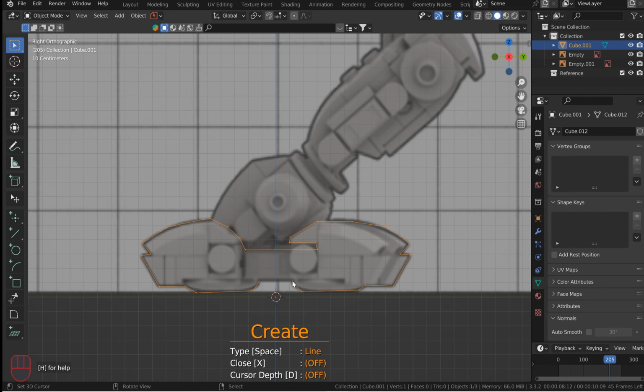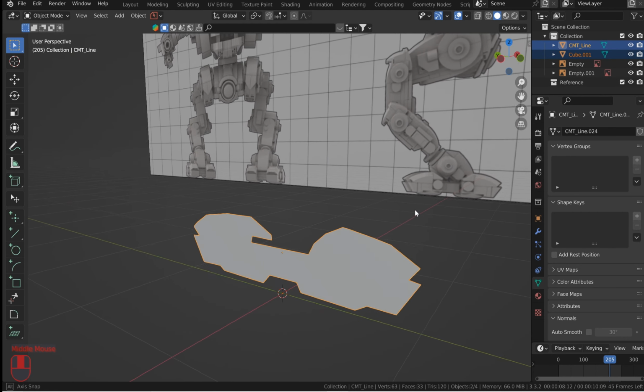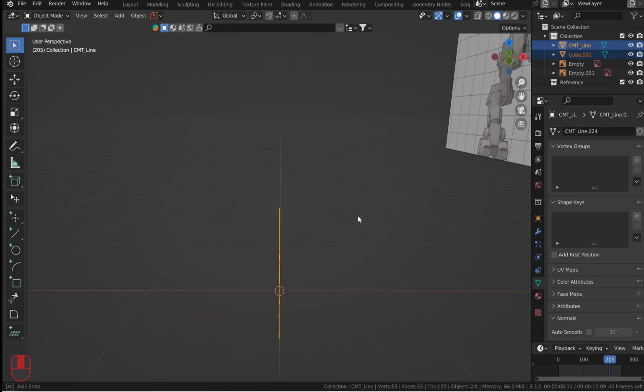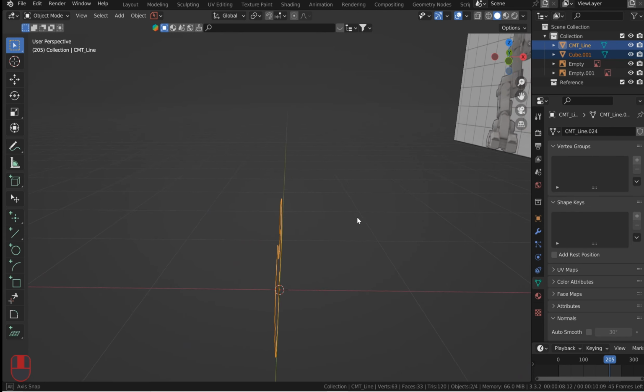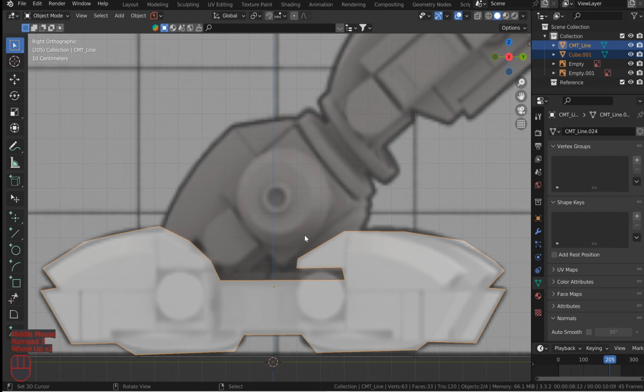something like that. Now right here, I'm not going to click anything else. I'm just going to hit X and then spacebar. Okay, and what that's going to do is it's going to create the face in that shape. Now we can extrude that out now, or we can do it later. It really doesn't even matter.